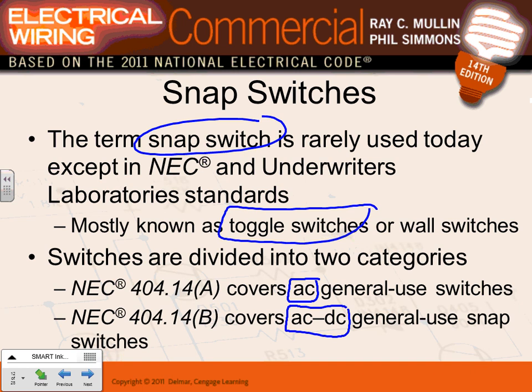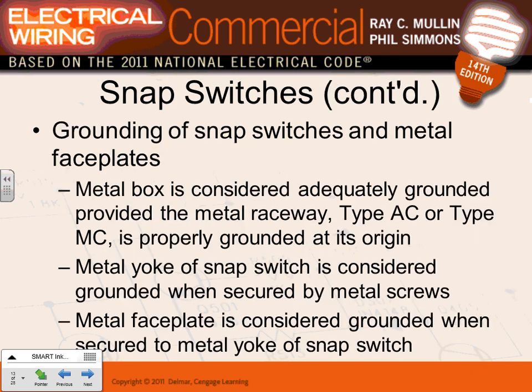Just remember this one. Your equipment, the switch, has to be able to break a circuit that's fed from an AC, so it has to be rated for that. Okay, grounding switch and metal faceplate. This talks about grounding it, guys.